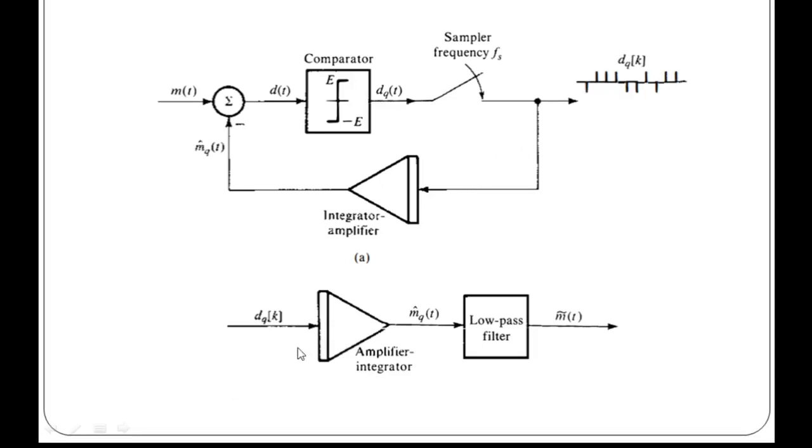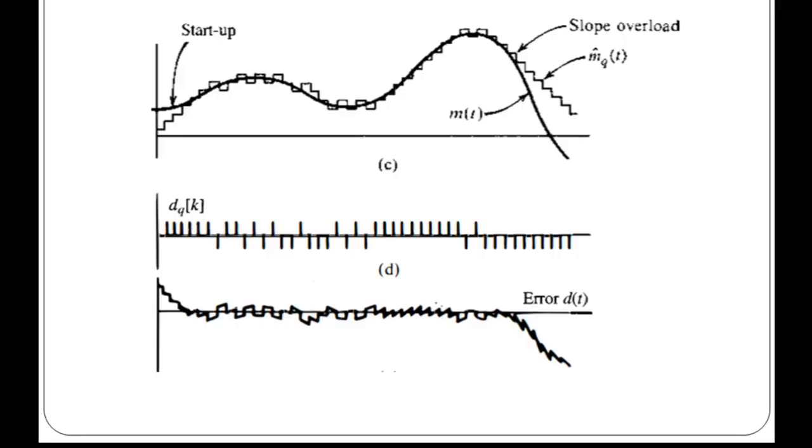At the receiver, we receive the signal, which is amplified and given to the integrator, and that will produce the staircase, because our input is impulses. The integration of an impulse is a step pulse. So the output of the integrator is a staircase, a step kind of response corresponding to each impulse, and it passes through the low pass filter. So this will be a continuous staircase response.